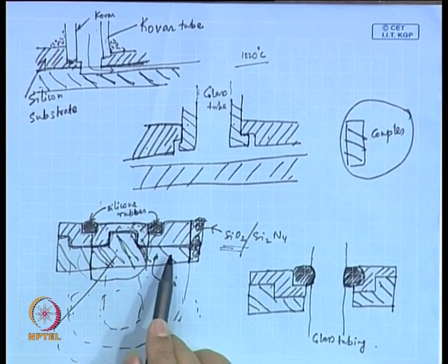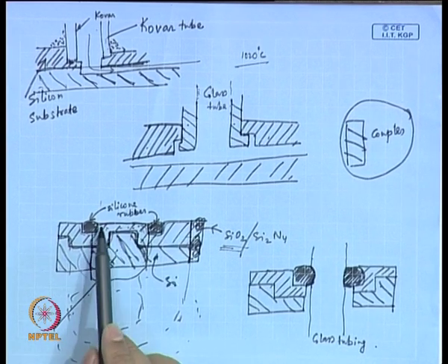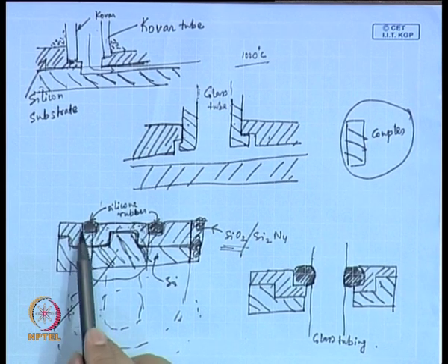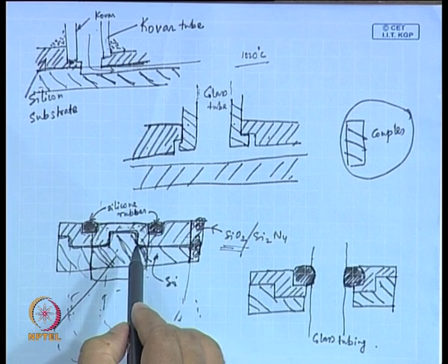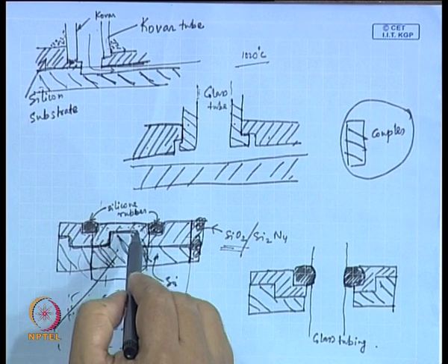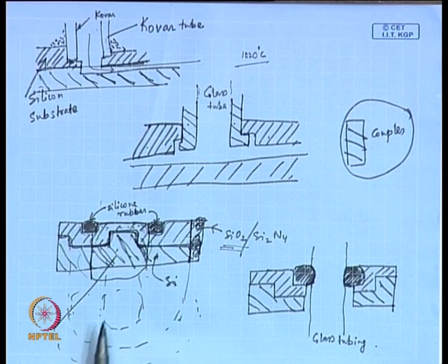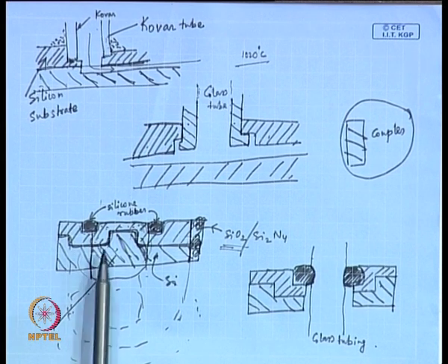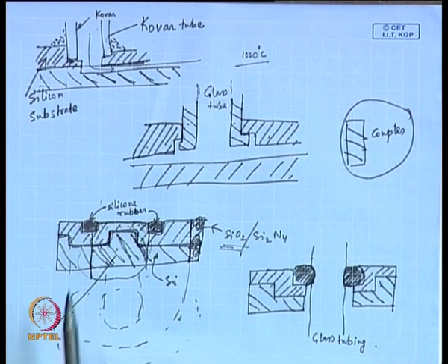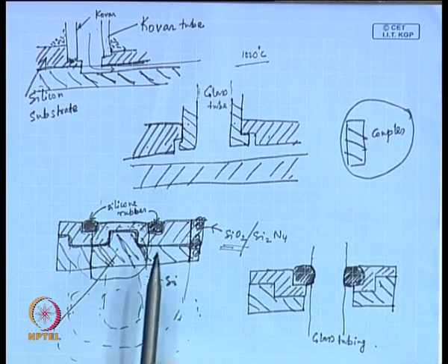So, this is the silicon wafer. You take the silicon wafer, put a layer on top, so that you form a cavity in these places, all right, and pour the silicone rubber, which is different, squeeze it into this, which is going to act as a gasket. Then you go from the back side, first remove the silicon layer. Removing silicon is very easy, it's not at all a problem, but SiO2 is difficult to remove. For that you have to go for dry etching, a stronger etching technique, and that you do. And then once you remove this whole material, what you have is